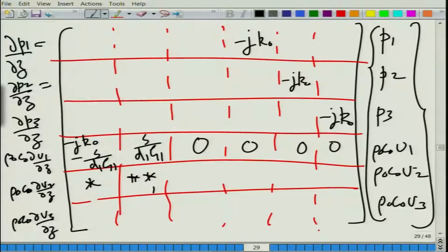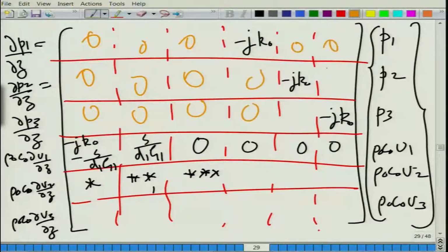So, I will put this, and then I will also put another triple star mark here, and I will tell you what these expressions are, and in the meanwhile wherever there is nothing, it is 0. So, like I said, it is all initialized with 0. So, 0 0 0. Now, the entries pertaining to the continuity equation in the third duct or the second perforated pipe, that is your outlet pipe.